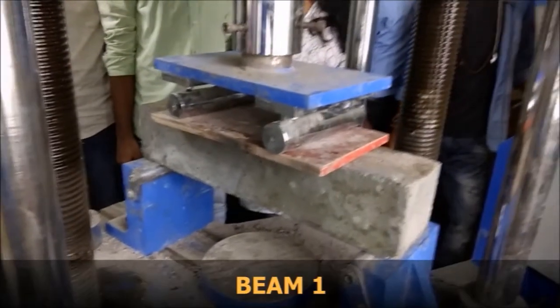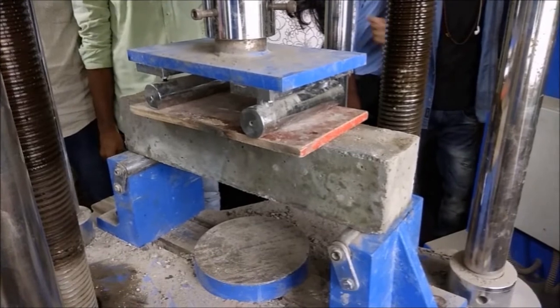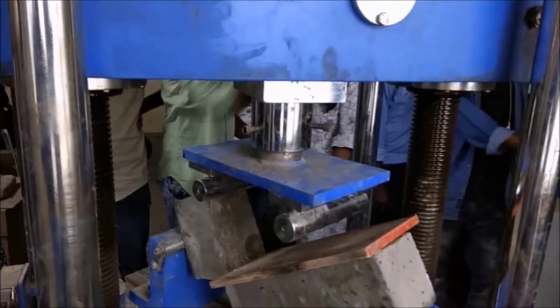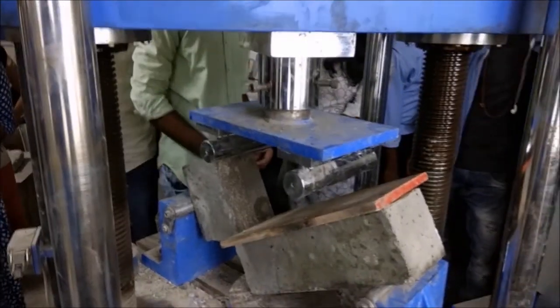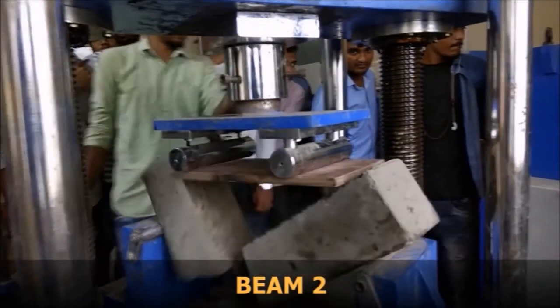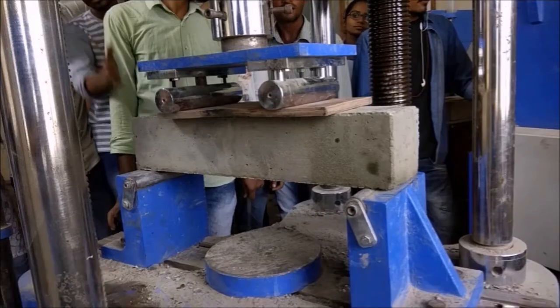Now after 28 days of curing, we will be testing the beams in a lab. As we see, due to the 3-point loading, this beam has failed. Now there you can see a wooden plank, and that is to ensure a uniform distribution of load, to ensure the pure bending.